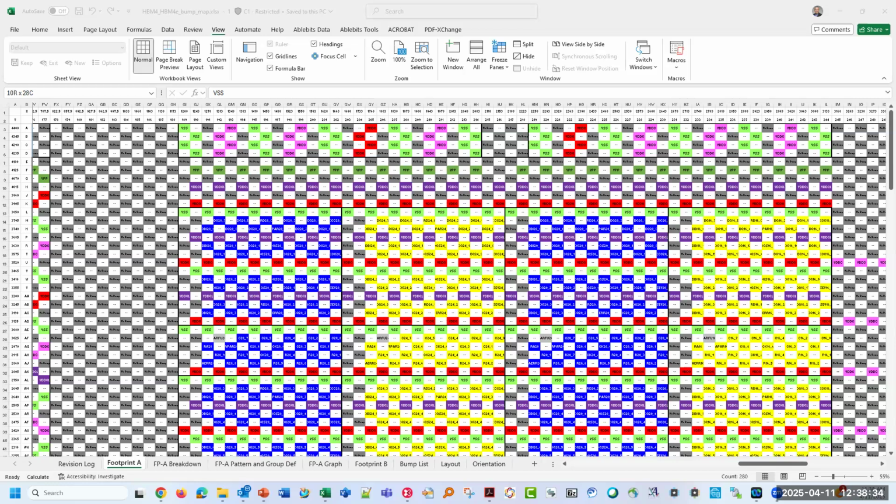Now, why I brought that up is because eventually, when you're shrinking the bump pitches, the interposer will be very tightly integrated, right? So now what you said, there could be a misalignment there. And if Deca is ever going to target that misalignment through creating notches or creating routes in this case to map the interposer with the die, then we should be ready to support that. But why did you ask that question, whether the presence of a route there matters or not?